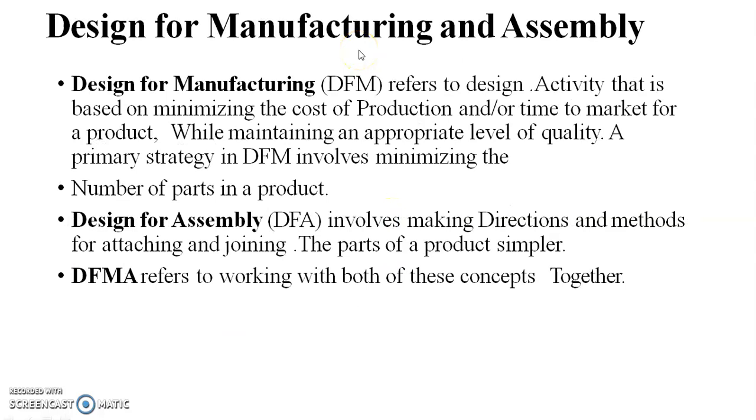Then the next case we are going to discuss is design for manufacturing and assembly. Now, design for manufacturing, the DFM, refers to the design activity that is based on minimizing the cost of production and or time to market for a product while maintaining an appropriate level of quality. A primary strategy in the DFM involves minimizing the number of parts in a product. This is the general basic guideline about design for manufacture. In this activity we minimize the cost of production or the time required to market a product, while trying to maintain the optimum level of quality.